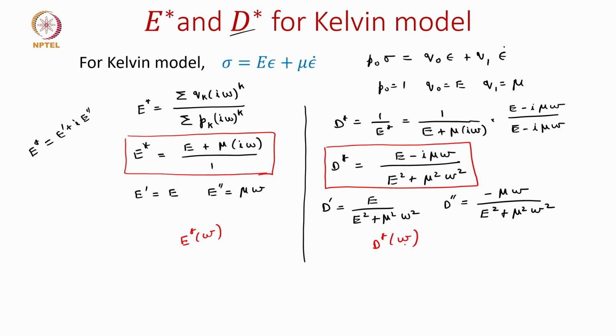So once we go to the next slide, that is what we will see, how these values change with frequency. So once we talk about E star, without saying it goes both for the storage and loss modulus also, these are all functions of the frequency. Similarly, the storage and loss compliance are also functions of frequency.